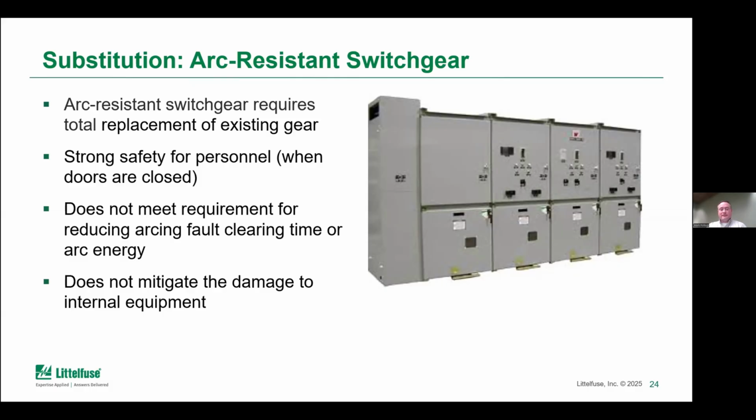Of course, as long as the doors are closed. So if somebody's doing maintenance on the panel and the door is open, then that arc mitigation is just not going to be there. One other cautionary item is, of course, if anyone has tried to do any modifications to this equipment or change a component, they may have compromised the original manufacturer's arc mitigation measures. So that's something to be aware of as well.